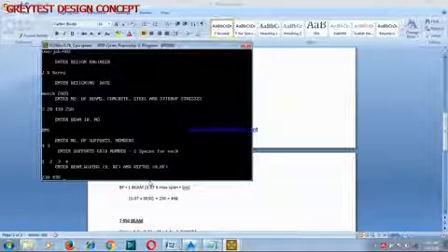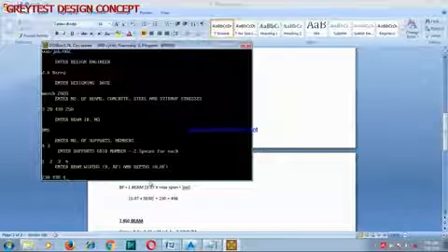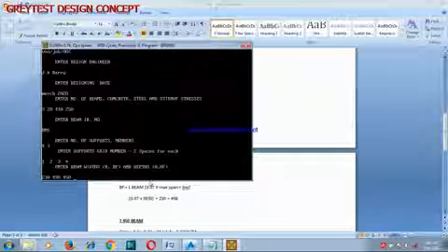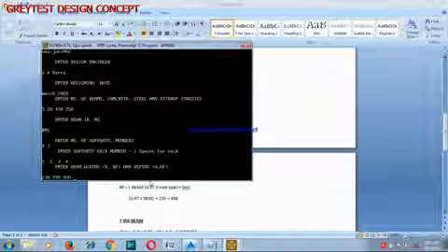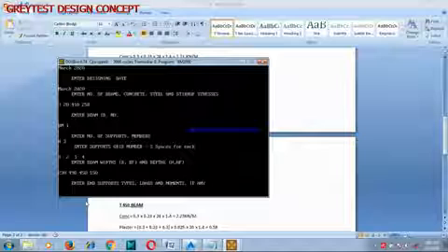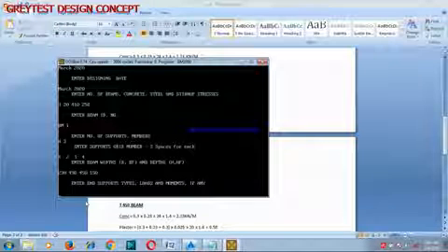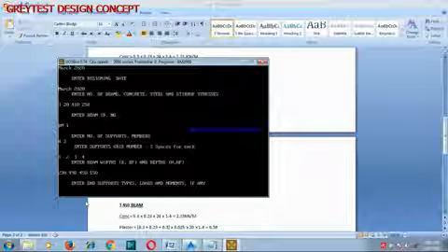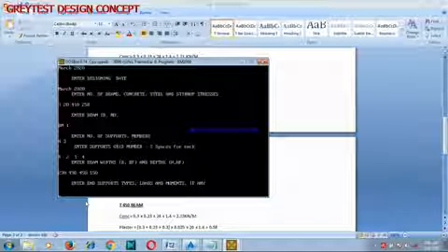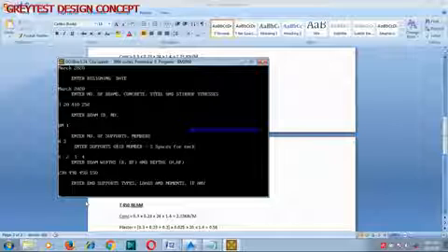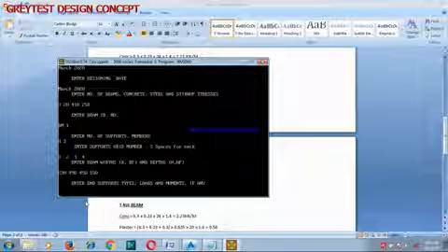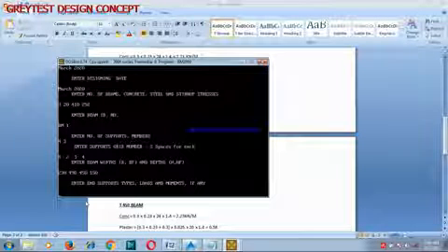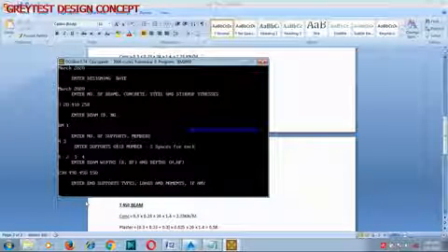Now the height, that's the depth of the beam, is 450. Now the support type: we have different kinds of support. For pin, cantilever, and free, we are going to use 0. For fixed or built-in support, we are going to use 1.